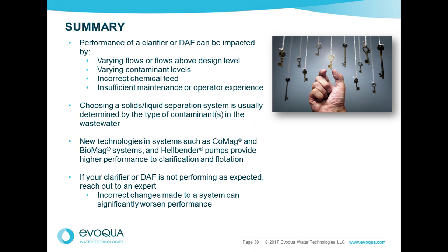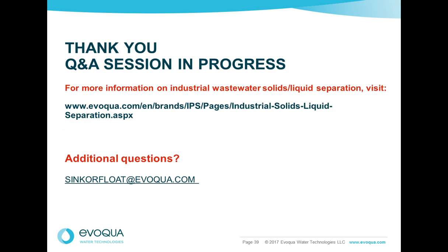And Chuck, I'm actually going to start off with you. So the question is, how do you determine if you should install a clarifier versus a DAF? Alex may have to jump in on this one a little bit later, but I'm a little bit biased because I am a DAF person, but it depends on the application. If you're dealing with very heavy solids that readily settle, then a clarifier is probably the right approach.